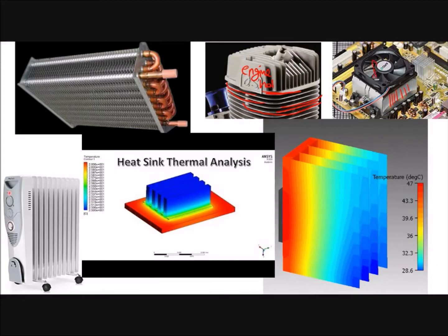And we have also a fan here. The fan increases h and the fins increase As, so we will have good heat transfer. And also in heating systems, we have the fins here. There are also three-dimensional fins going into the page. And also you have the car radiator. There are lots of fins here.